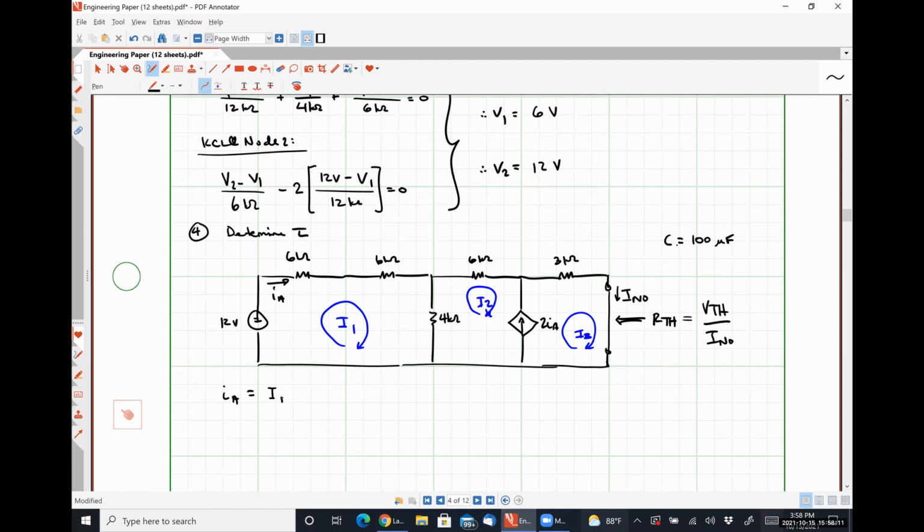All right, I have a current source. What is my current source relationship going to be? Exactly right. So from this, we could say that twice I1 plus I2 minus I3 is equal to 0. Somebody tell me if I did my algebra wrong. I just substituted in I1 for IA, moved I2 over to the left-hand side, moved I3 over to the left-hand side.